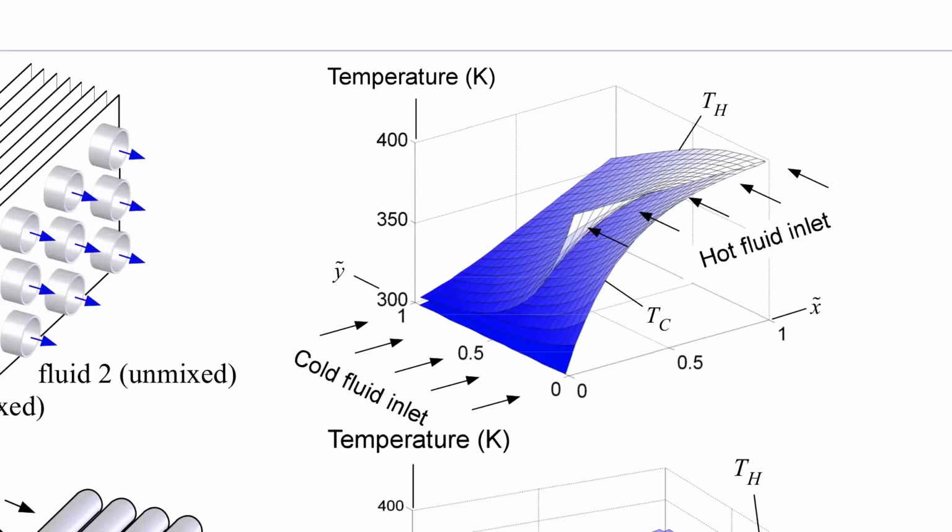So we have cold fluid coming in here. And remember, we're not allowing this fluid to mix. So as it goes across the heat exchanger, it's going to start heating up that fluid. And eventually it comes out over here. So if you're that bit of air coming in right where the fluid is hottest, this is your delta T. As you move along, your delta T gets smaller and smaller, and you end up converging with your final outlet temperature up here. This is unmixed. Over here, you can do the same thing, but your delta T is pretty small, and so you're just moving these both up in parallel as you go out here.